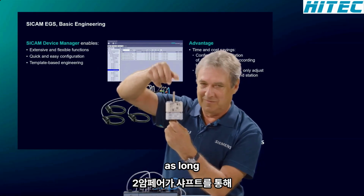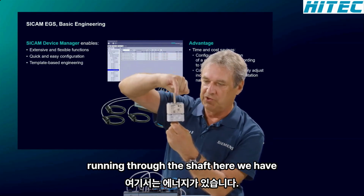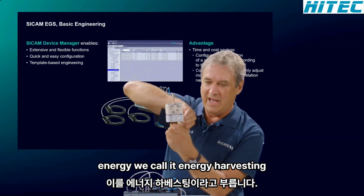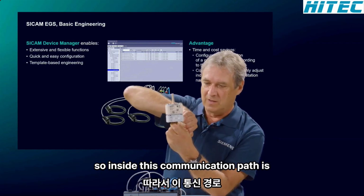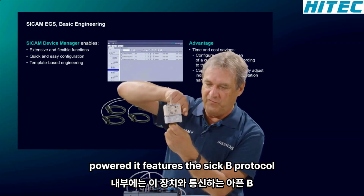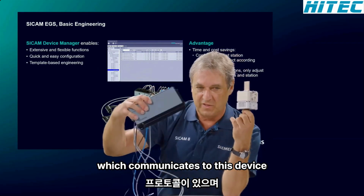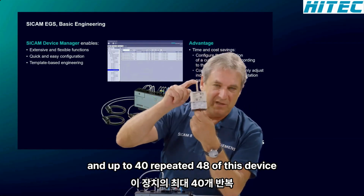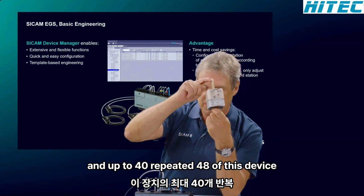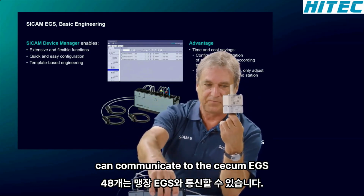As long, I told it, as long as 2 ampere are running through the shaft, here we have energy, we call it energy harvesting. So inside this communication part is powered. It features the Zigbee protocol, which communicates to this device. And up to 48 of this device can communicate to the SICAM EGS.